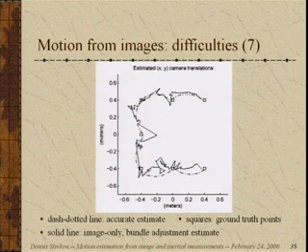And what you're seeing here is the XY view of the robot's workspace. So you see this cloverleaf pattern that's basically the correct motion, which is that smooth dashed dotted line. The 7 boxes there are the control points for the motion. So we told the robot to go through those 7 points and basically execute a circular arc between them.